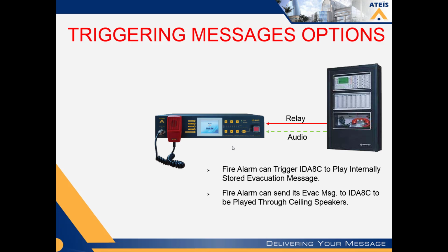So let's say you got a fire alarm system with voice evac, and you've got voice evac speakers in just certain areas. Maybe it's in what we call areas of assembly, which by NFPA 101 Life Safety Code, if it's characterized as that, like a cafeteria, an auditorium, and a gymnasium, you may have voice evac panels already in there, and or they just may have voice evac speakers connected to the main fire alarm panel.